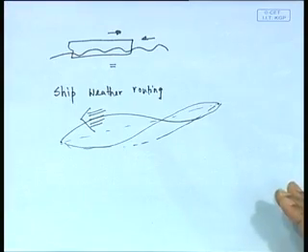So, we will talk next class about certain empirical formulas of added resistance and how you determine added resistance in an irregular sea. We will find that in added resistance we are not concerned with the 1/3 significant value etc., but with the average value, because it is the average value of increased resistance that we are more interested in. This we will discuss in the next lecture, along with some ideas on seakeeping criteria for design, polar plots and things like that.